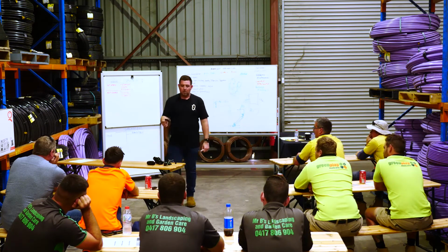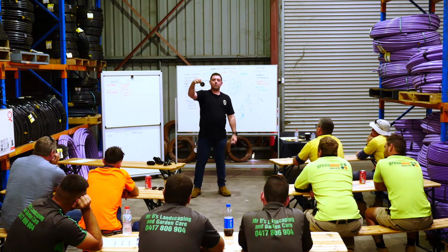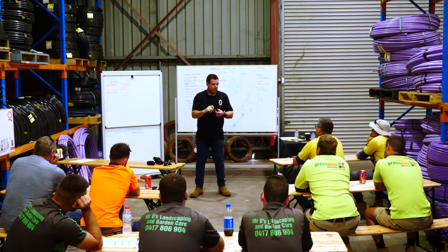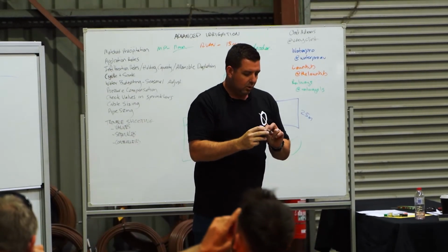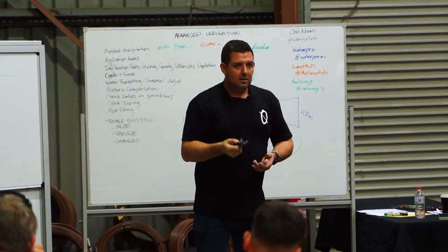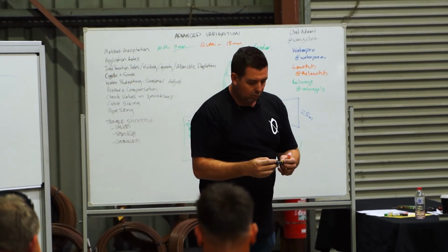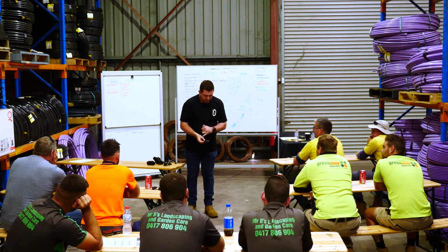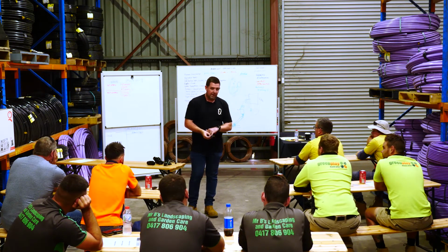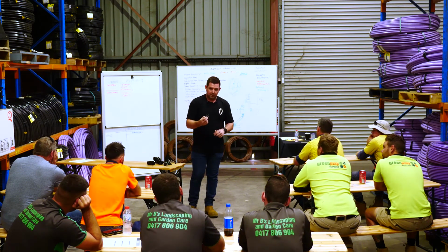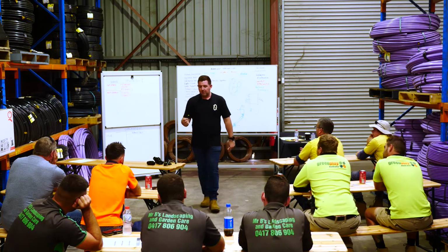While you're looking for that rock, you check the integrity of the diaphragm. Every diaphragm looks similar, but they're all different. If there's a problem with a diaphragm, you're going to see it. They're consistent around the whole diaphragm. If there's a split or a crack or damage from any stones, you'll pick it up straight away.